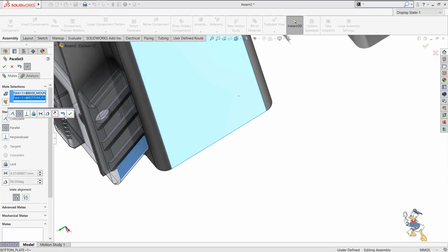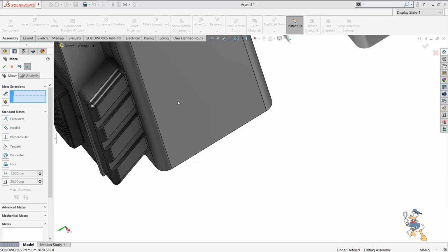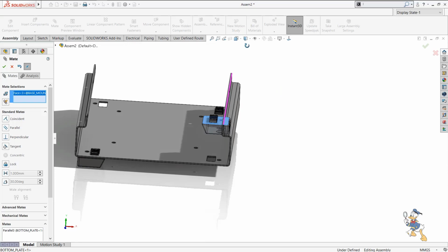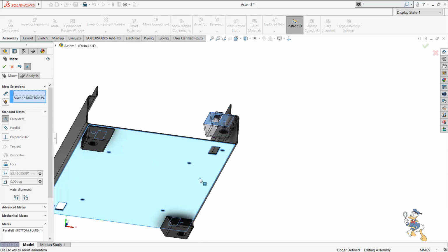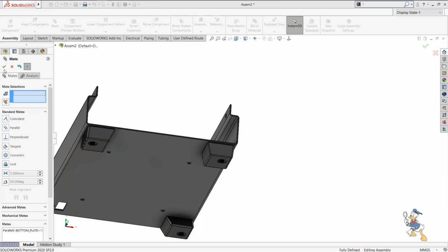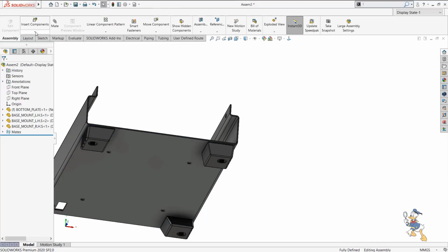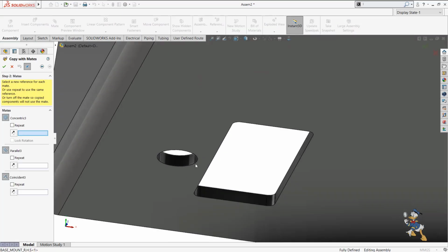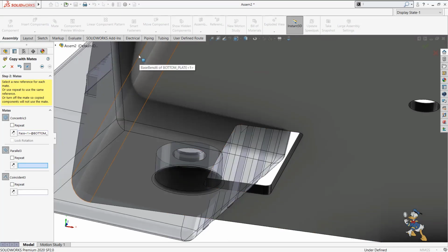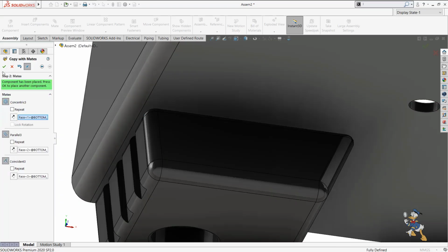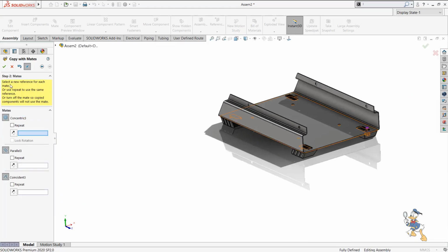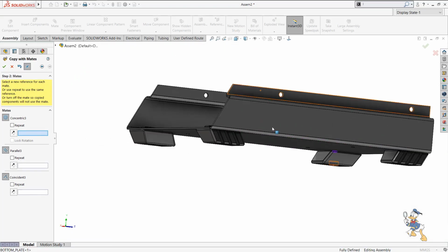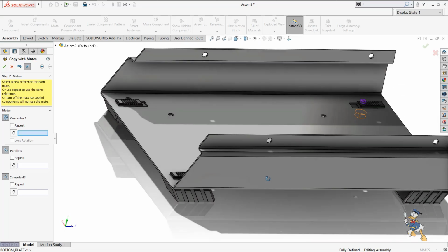As it is opposite, I check it as opposite, and then I make it possible by selecting the coincident face value. So yeah, this is available for us. I can check it out. I can copy this feature with mates as well. I provide the mate features which we have provided for that, and we will generate this kind of assembly. So we have started the assembly by mating the components and providing the values.